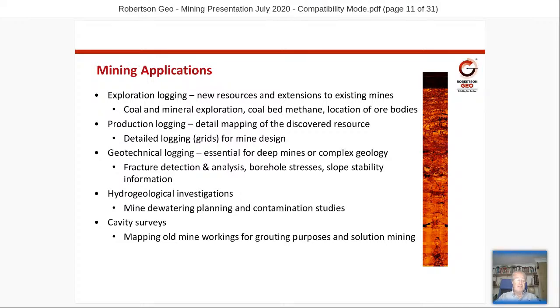And cavity surveys. One of the things we find in the UK, there are many old coal mines and shafts around the country that now find themselves under areas of residential development or light industrial development. And it's critical to map these old mine workings for grouting and remedial purposes, and in some cases solution mining. So there are tools that we can use to determine the location and the size of these cavities.